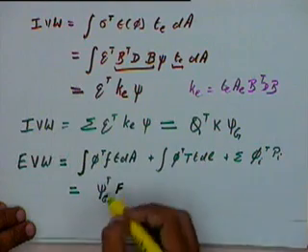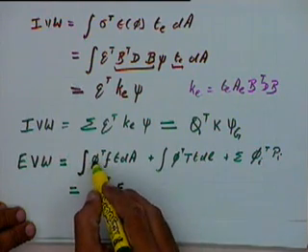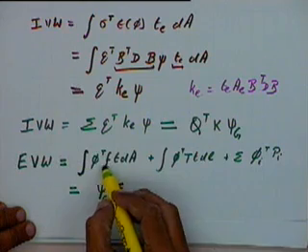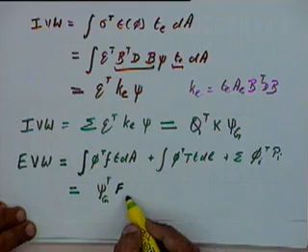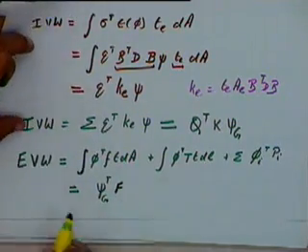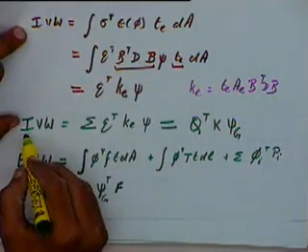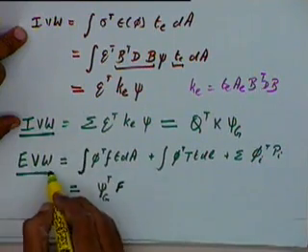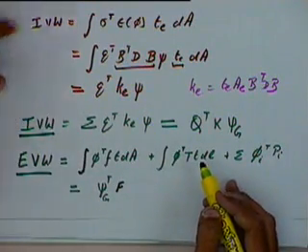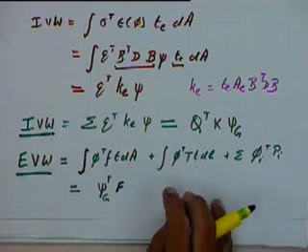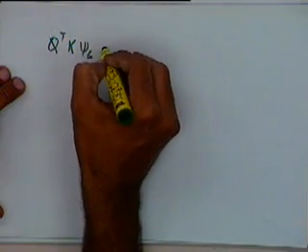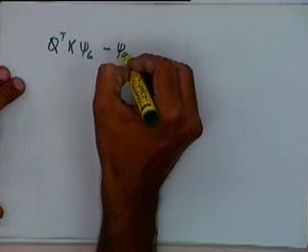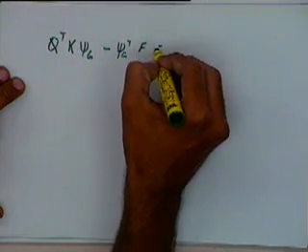Okay, the process will again be the same. We'll put expressions for phi, we'll put expressions for f, carry out the integral, and we'll assemble these force matrices. Okay, so the Galerkin's approach will give us that internal virtual work done is equal to the external virtual work done. So this will effectively give us an equation of the form Q transpose K psi global minus psi global transpose times F is equal to 0.